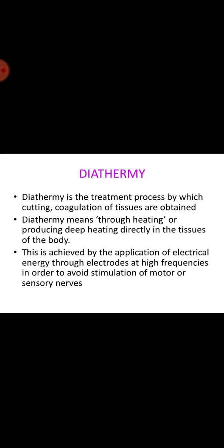involving cutting and coagulation. The frequency of currents used in surgical diathermy units is in the range of 1 to 3 MHz, in contrast with the much higher frequencies employed in shortwave therapeutic diathermy machines. And this frequency is quite high in comparison with that of the 50 Hz mains supply. This is necessary to avoid the intense muscle activity and the electrocution hazards which occur if lower frequencies are